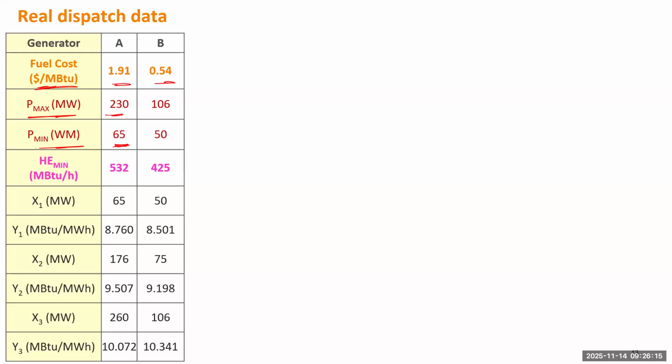Once you decide to start any power plant, you need to quickly run or follow a certain ramping up curve until it can reach the minimal generation. That one cannot be interrupted. You have to continually increase the output until that minimal value. Then you have more flexibility to change the generation between this minimal and maximal.